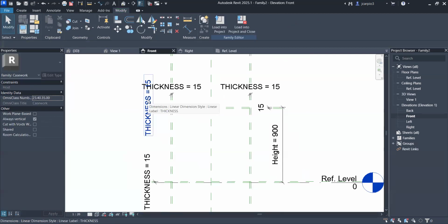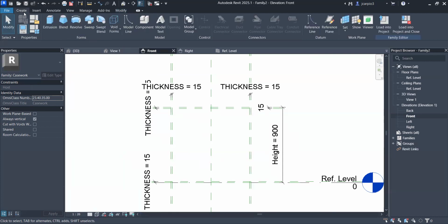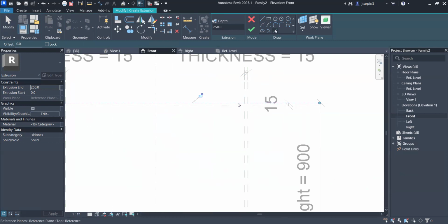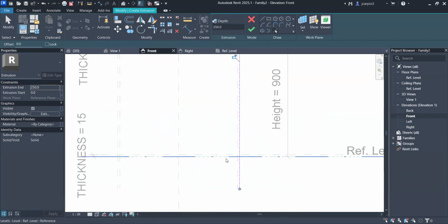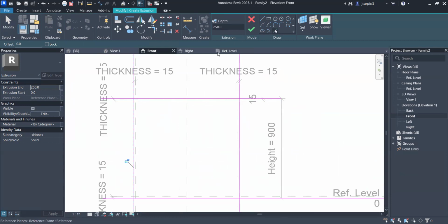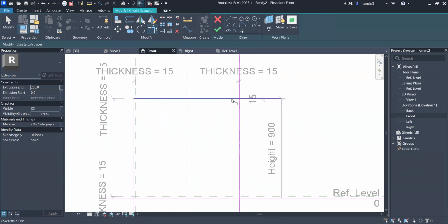After doing this thickness, you go to Create Extrusion. So first you have two rectangles to draw. For the first part, you're gonna need the option of Pick Lines and select all the original references in this family and hit Trim or Extend to Corner for all sides.